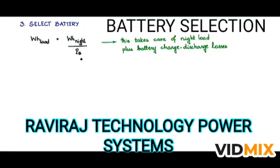However, just now we discussed the number of days of autonomy. There can be cloudy days, there can be contiguous days without significant amount of sun power. Now let us say that NA, number of days of autonomous operation, number of days of autonomy, is not zero, which means you could have one day without the PV panels participating. There could be 2 days without the PV panels participating, and so on. So if we take NA not equal to 0,